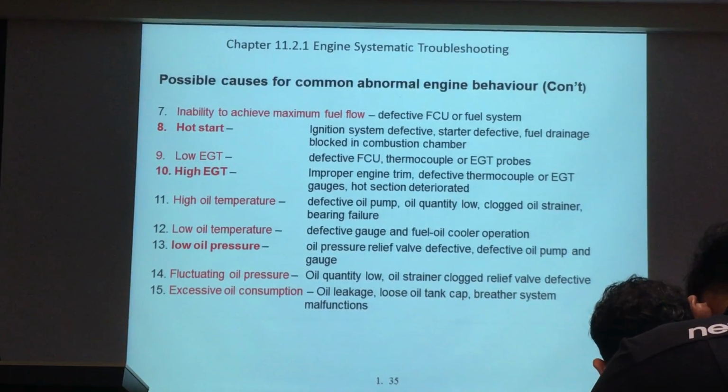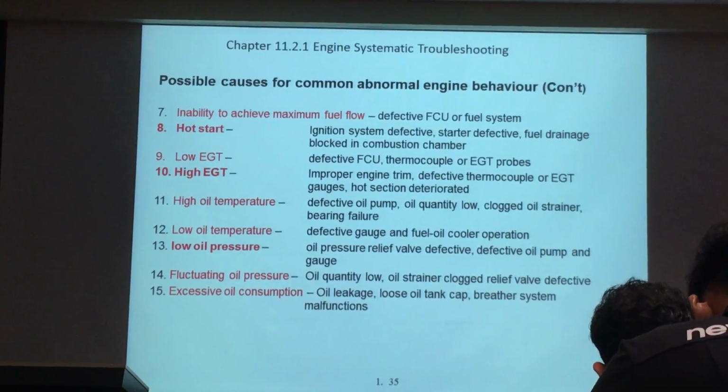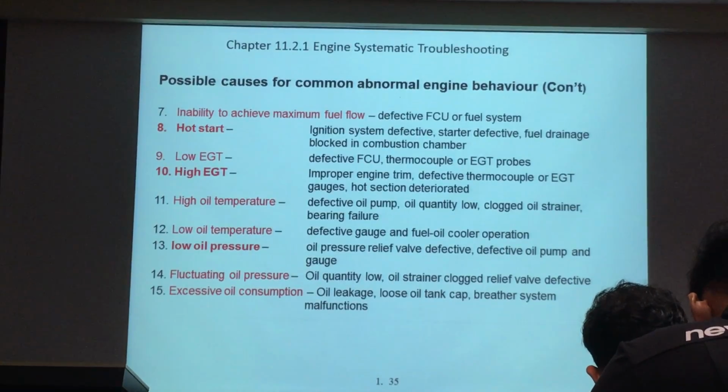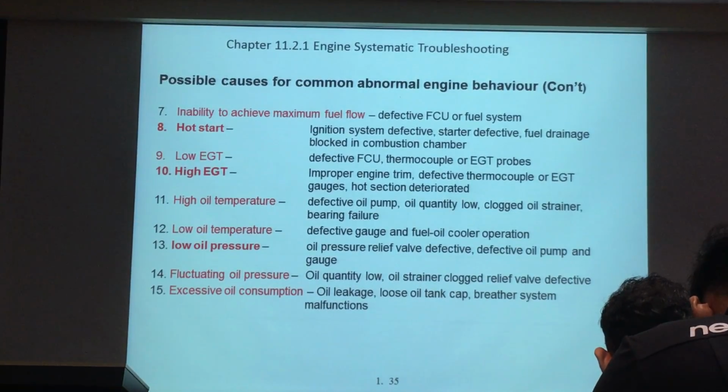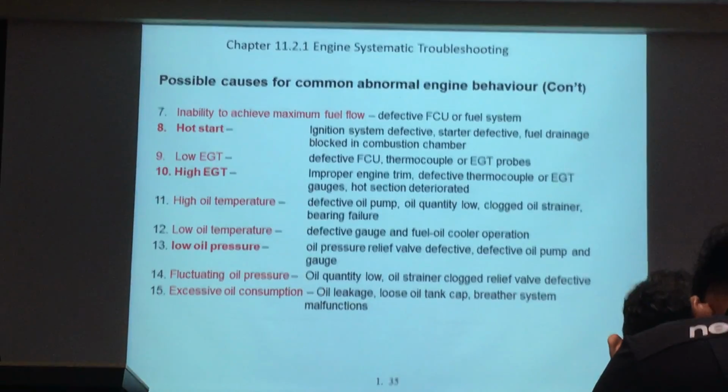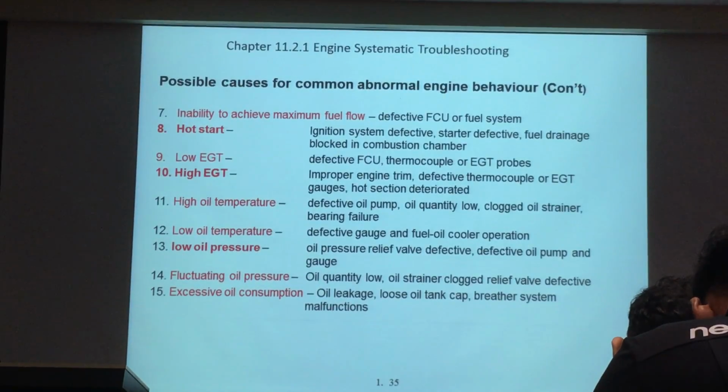So what is the cause of low oil pressure? Oil pump failure, or your oil filter clogged so oil cannot come in. Or maybe a defective gauge gives you a wrong reading: actually there is oil pressure and oil flow, but the gauge gives you a wrong reading. But the pilot will still treat it as positive.